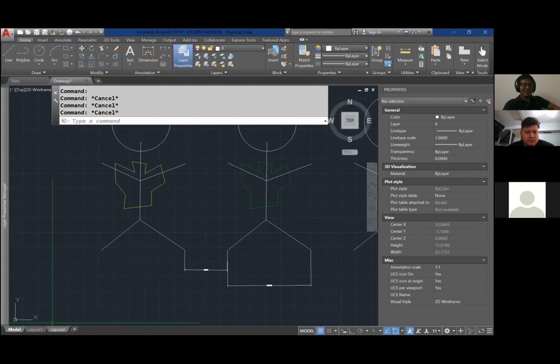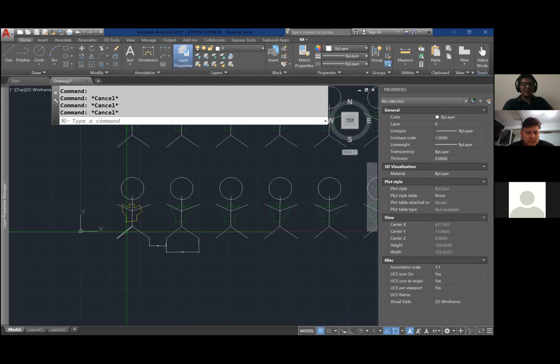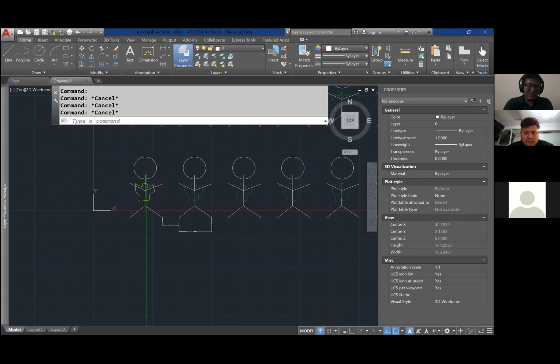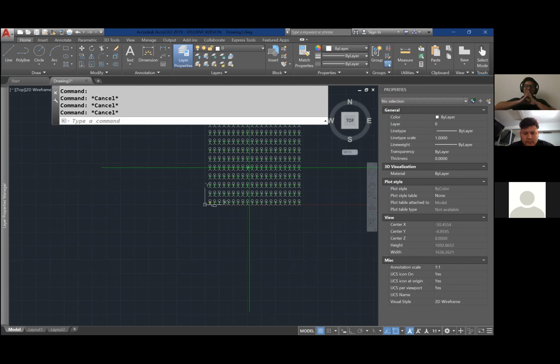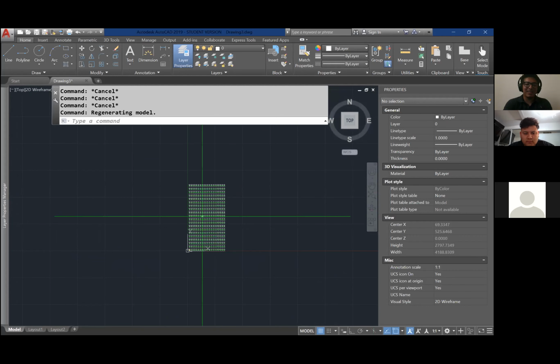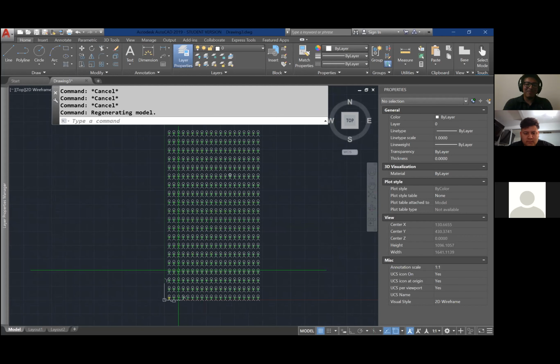Now, not necessarily the fun part, but a little thing you have to know if you want to do this is model space and paper space. So this right now, where we're doing all our drawings and messing around and where you're going to be doing all your actual project work, is called model space. This is where you model everything, right? Oh no, I drew a lot of these guys. Yeah, this is model space.